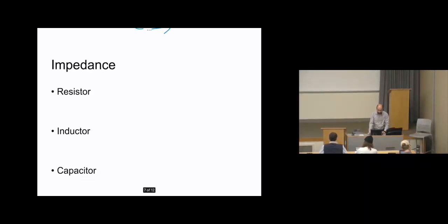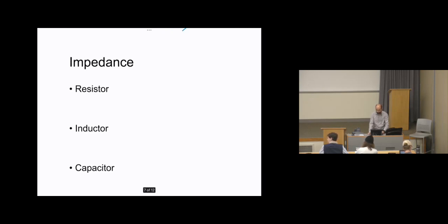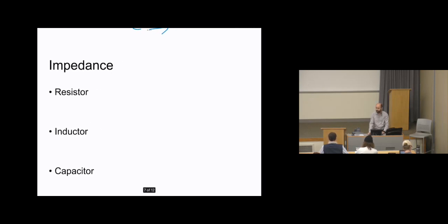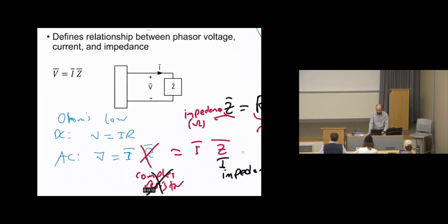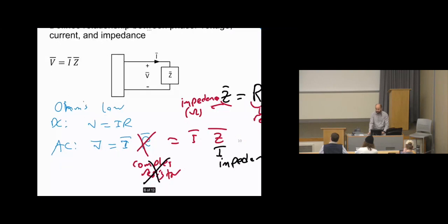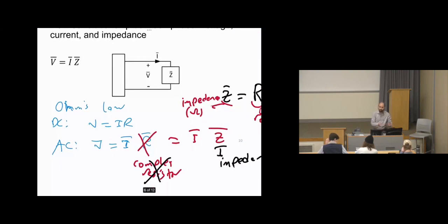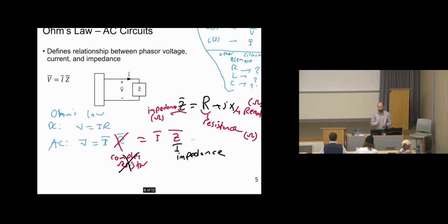Let's continue on the phasor domain, AC circuit analysis. So last lecture, we discussed how to make phasor domain and phasor domain inverse for both voltages and currents. Then we discussed the impedance, which is something similar to a complex resistor, but we will not consider it as a resistor because the resistor definition is related only to real parts.